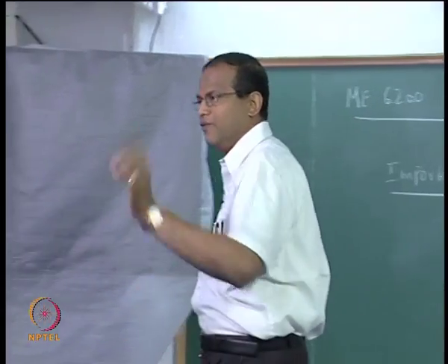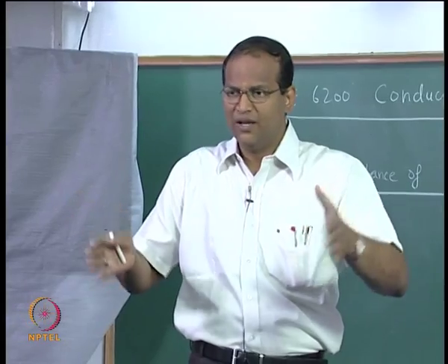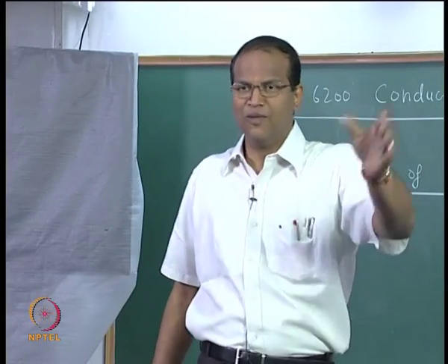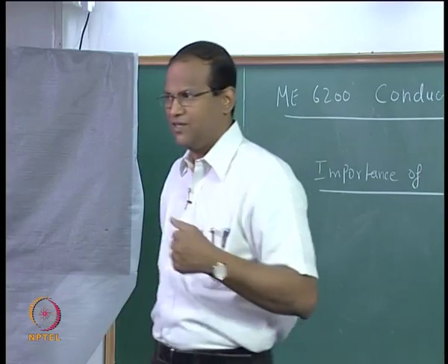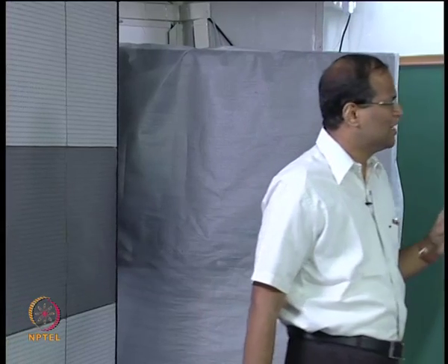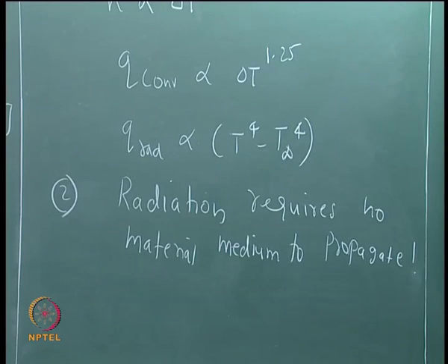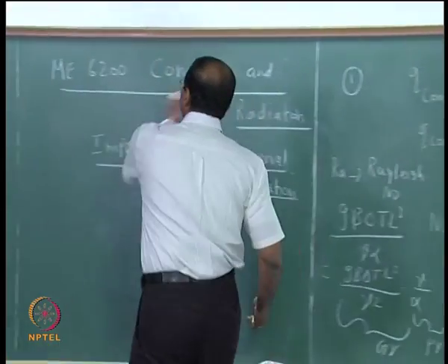Forget for the time being that the gap is so small that natural convection does not set in, but these two glass plates are at some temperature, and in between, even if there is vacuum, there will be radiative heat transfer. Are you getting that point? So radiation requires no material medium to propagate, therefore it is not easy to say that under these media radiation is not important, we can neglect. Point number 3,